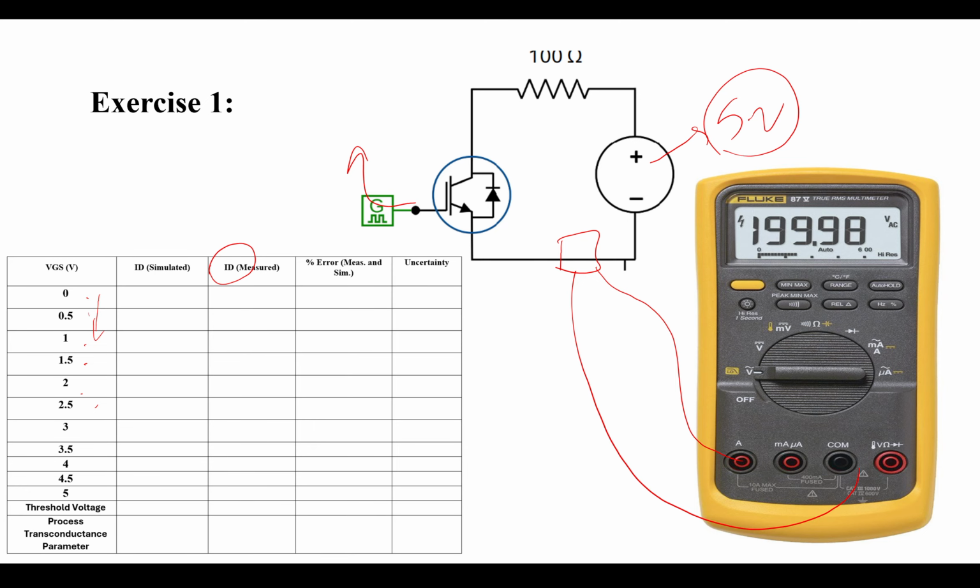Now you apply the voltage, increase it little by little, and read the current. There is a point when you increase the VGS that suddenly the current starts to jump. Suddenly it starts to conduct a relatively massive amount of current compared to the points before that. That level is the threshold. Are we good?